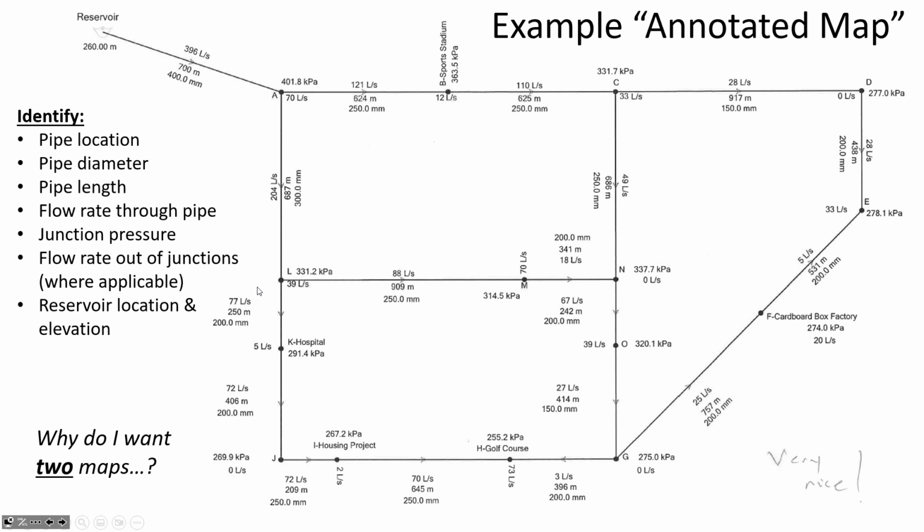I think it's probably better to do the flow part first and then the zero flow, but knowing where to put it is kind of iterative, because you don't want to put the reservoir at an elevation of 300 if that's going to make the pressures everywhere else too high. So maybe calculating the maximum elevation you can go for the reservoir would be a good place to start. So actually maybe the static condition and then the flow condition.